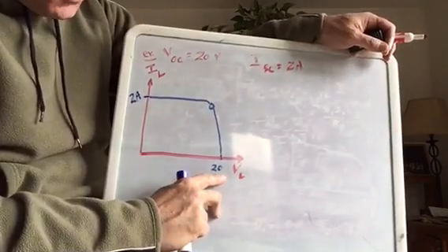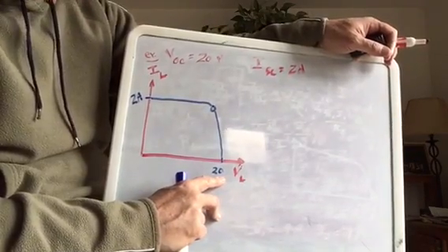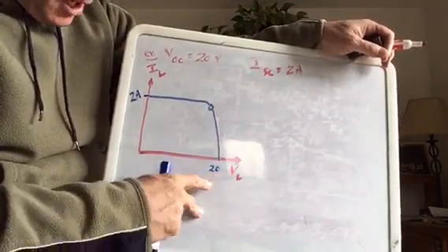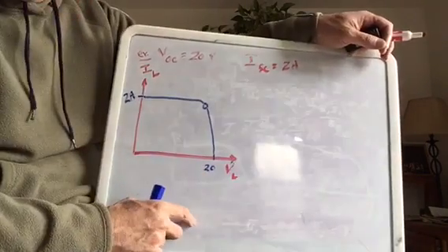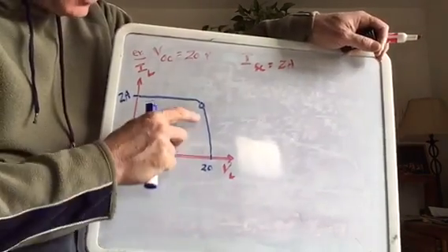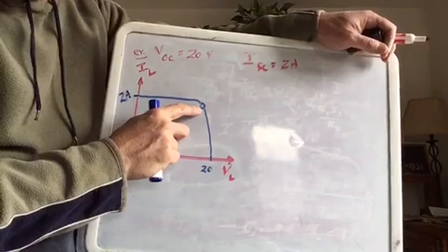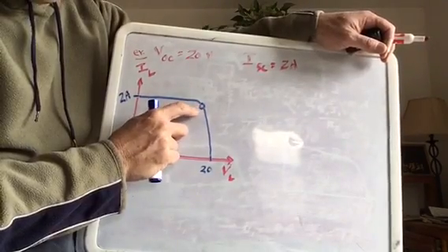And if we have an open circuit, we're going to read 20 volts across the leads for the PV panel, and we're going to have 0 current. So that is typically what's given by a manufacturer. This point right here, this circle, would be the maximum power point, and more on that later.